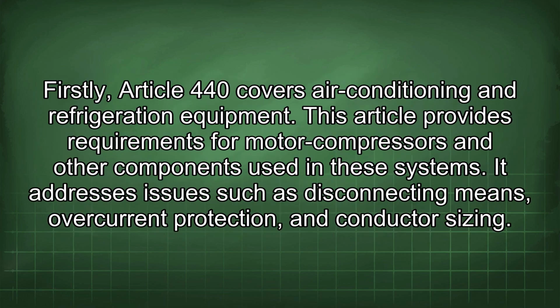Firstly, Article 440 covers air conditioning and refrigeration equipment. This article provides requirements for motor compressors and other components used in these systems. It addresses issues such as disconnecting means, overcurrent protection, and conductor sizing.